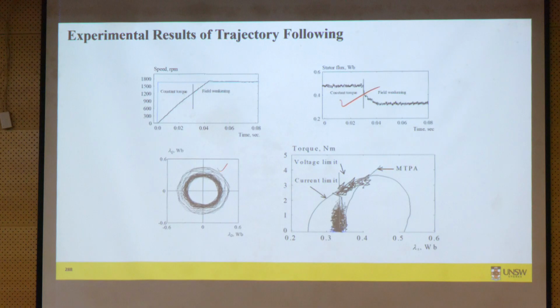And this is the reason why DTC is problematic, because there are a lot of high frequency harmonics as well. That means your flux linkage has ripple, so that translates to ripple in your torque. So you get high torque ripple and high ripple in your flux linkage, causing your motor to not run smoothly under DTC with a switching table.